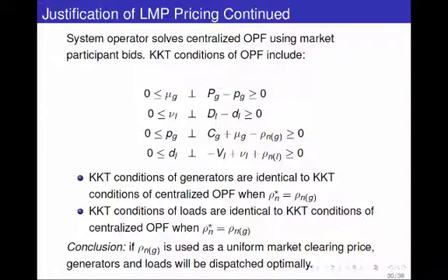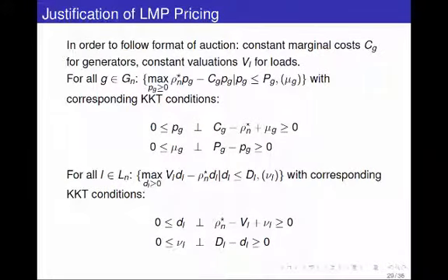What the system operator is going to do is collect all these block bids and solve the OPF, the optimal power flow problem. A subset of the conditions of the OPF that we saw in slide 4, I think, of today's lecture was this set of conditions. So these conditions also show up here. And basically, if I select this rho star to be the same one that the optimal power flow problem gives me,